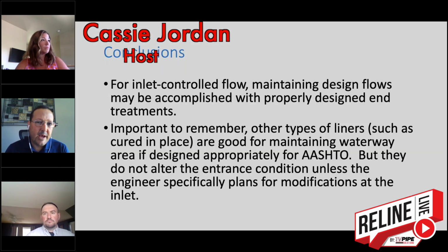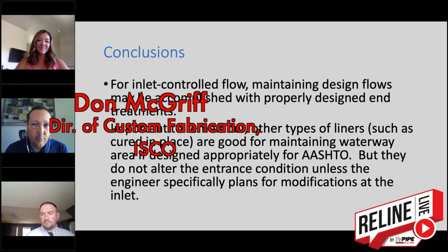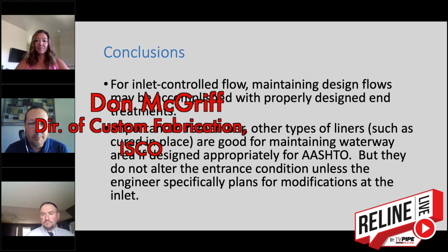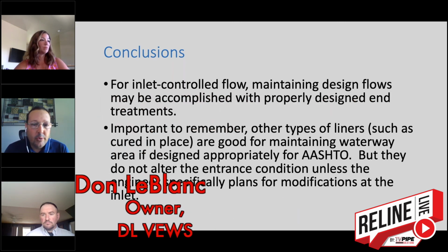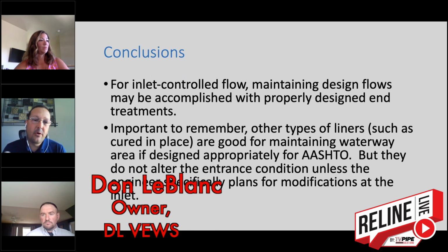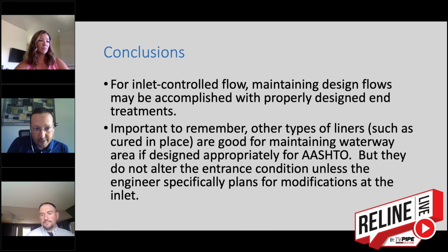I don't know that I had anything past this other than maybe a couple conclusions. So we're saying that, with the right inlet device, you can still maintain flows. One of the things that we argue against and we see is a lot of people prefer cured-in-place liners because they view that they're cutting the ID down less than they would with a plastic liner. And there's all sorts of other factors that go along with that, that we would argue against. Don, I'd let you work on those conclusions as well, as far as what you've seen.